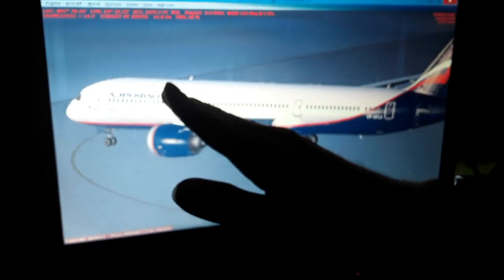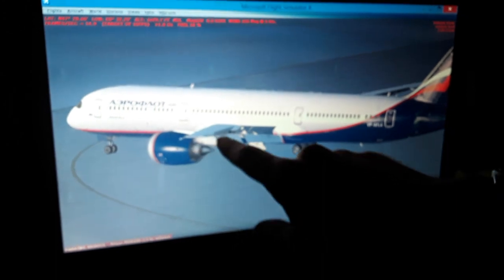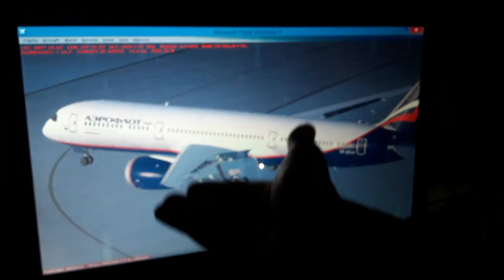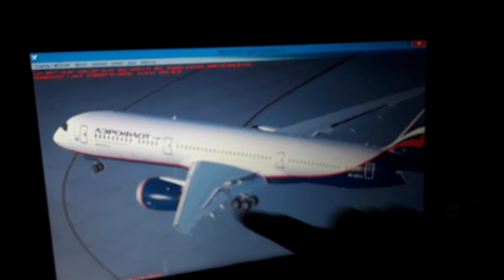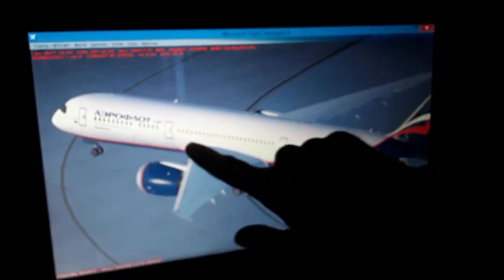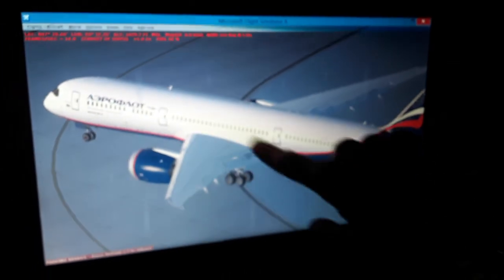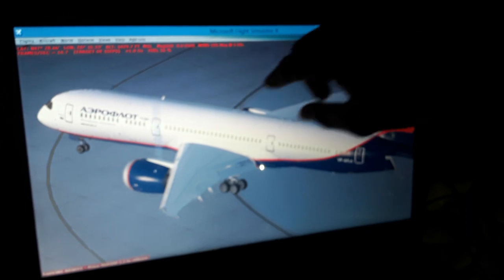We have also the angle of attack of the aircraft from the wings as we fly, so we have a lower airspeed flow below the wings, which creates higher pressure below the wings, which pushes the aircraft weight and wings up in the air. You can see also the top surface of the wings is more curved, so we have a higher airflow above the wings using the Bernoulli theory of fluids. So this creates a lower pressure above the wings, which sucks the aircraft weight and wings up into the air.